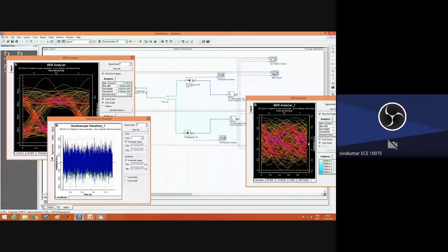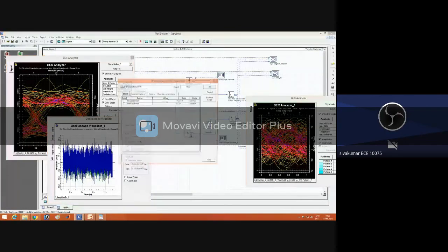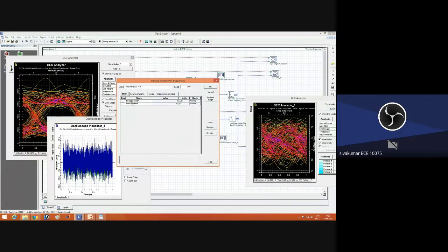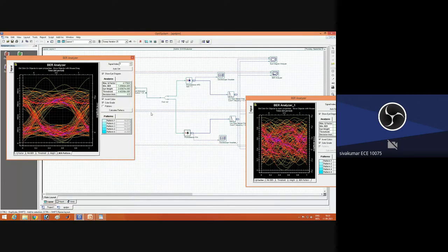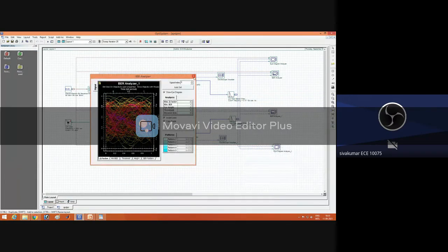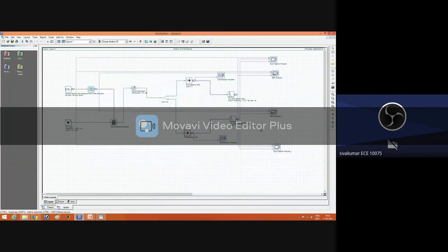Okay, whichever you choose, you double click on a photo detector. Here noise is there. Okay, here there are some modifications. Based on that, you just modify the values, apply the dark current values or responsivity values. You change this mode to sleep mode or normal mode. In this manner, you analyze the circuit, try to get the better maximum Q factor for this photo detector.